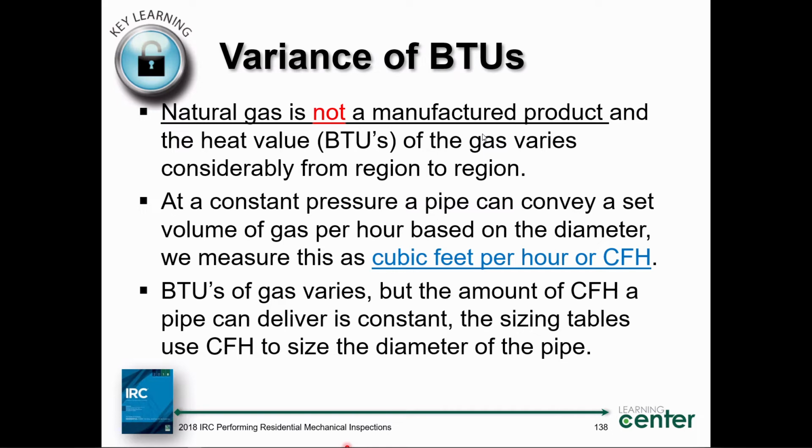Each and every one of those constituent gases, ladies and gentlemen, has its own energy rating. If I took pure butane, you know what the energy value of butane is? How many BTUs per cubic foot? It's about 3,000 or 4,000 BTUs of energy per cubic foot of butane.